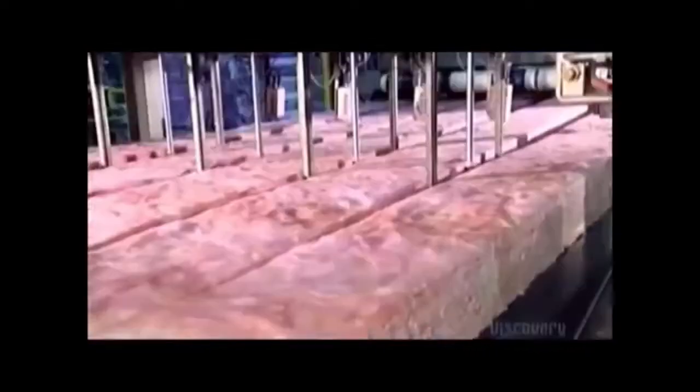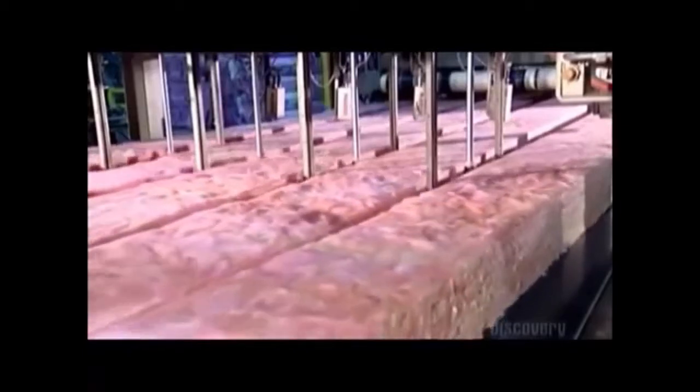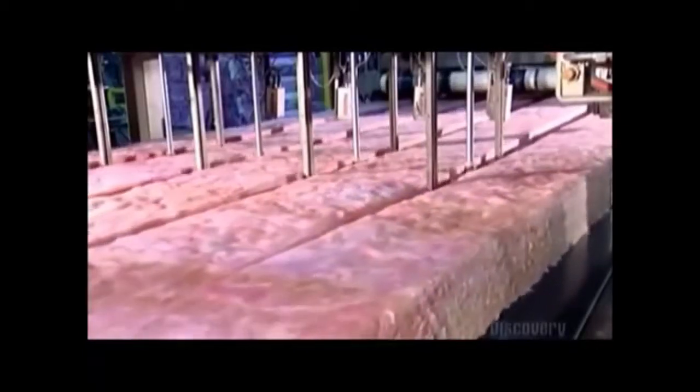Then a conveyor belt takes the mounds of sticky glass to an oven. Steel plates compress the pack as it enters the oven that's heated to 260 degrees Celsius. Hot air blows through it, setting the glue. As the pack exits the oven, circular saws cut through it, making 38 to 60 centimeter wide strips that are called lanes. The lanes pass by a series of poles that push them apart.